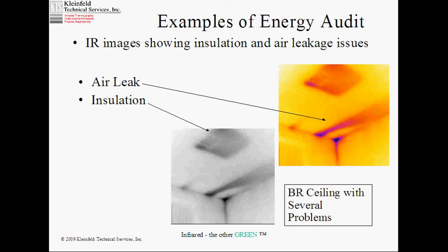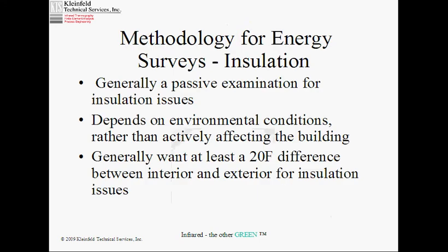You had to have a boundary around them. But it was a boundary around them, which this is not. This is flush to insulation on at least one side. And the boundary should in no way have been as large as that. So this is a misinstalled lighting system or misinsulated lighting system.